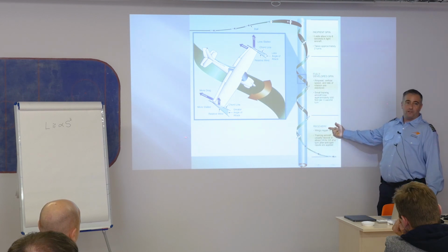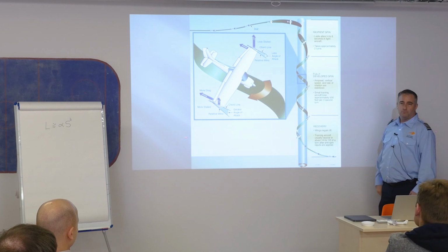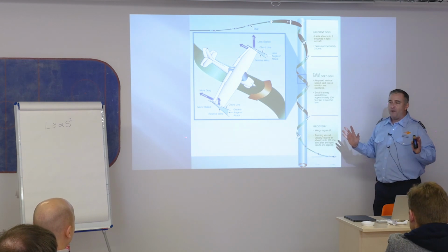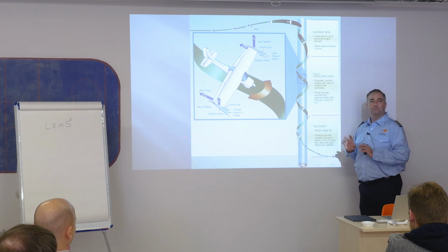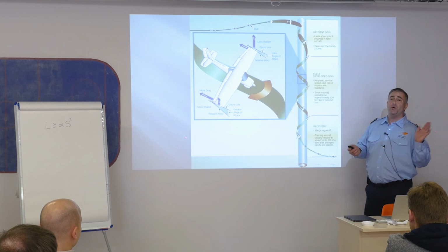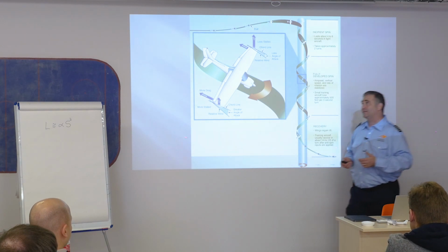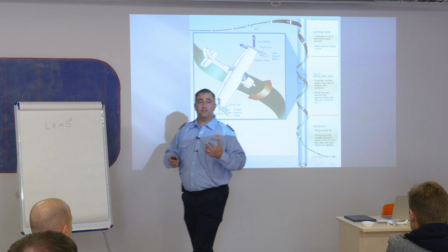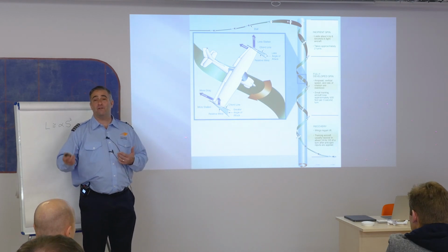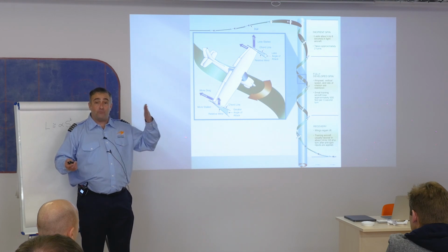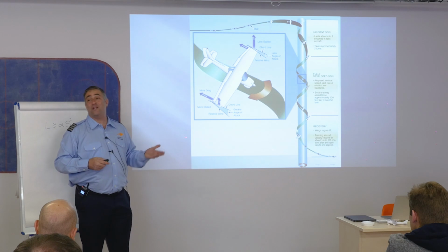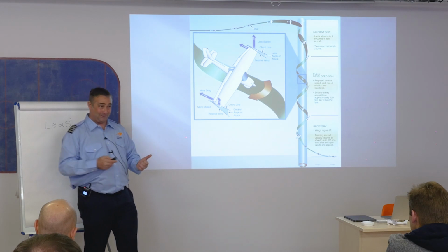And then the recovery. Just recover. They'll recover as soon as you release the control. A quarter to a half turn at the most. Okay. If for whatever reason you get confused or you get lost or you forget what to do, guess what? The instructions to recover from a spin are printed on the side of the airplane. You can just look and read it. It'll tell you exactly what to do.